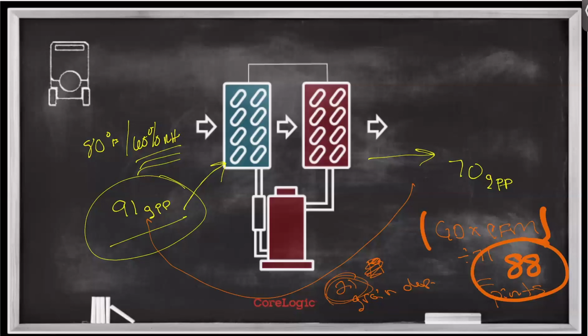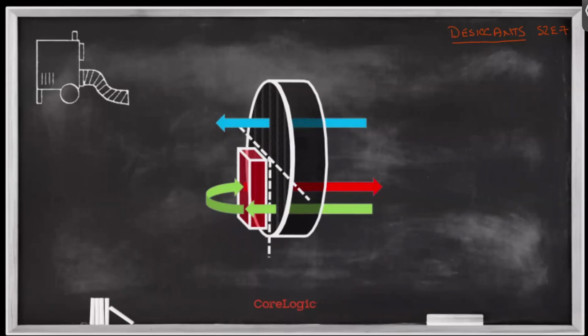I do want to talk a little bit also about other methods of dehumidification. In addition to refrigerant dehumidification, another methodology is something called a desiccant. Because of where we are on time, I'm not going to drive real deep into desiccants, but if you do have desiccant dehumidifiers that you are using occasionally within your fleet, and you want a much better understanding of how they operate, how to leverage their benefits appropriately, and what projects to use them on, there's a really good episode we did on that back in season 2.